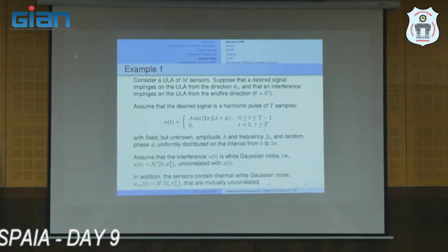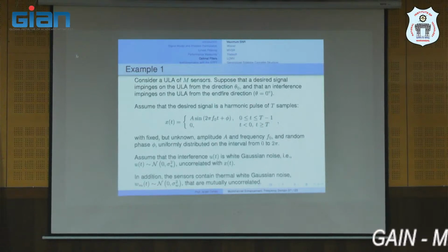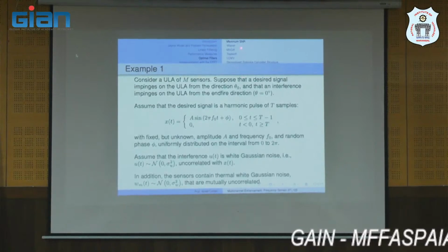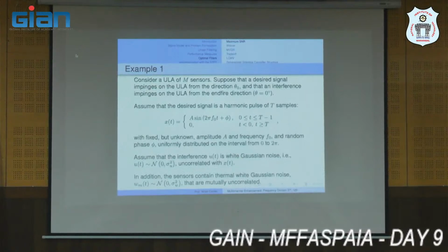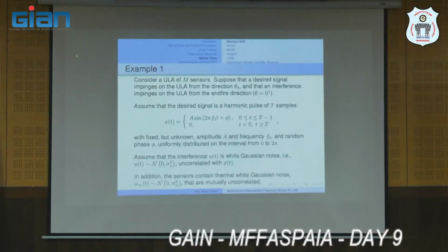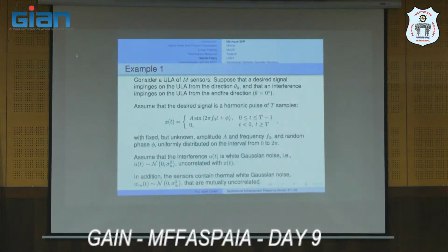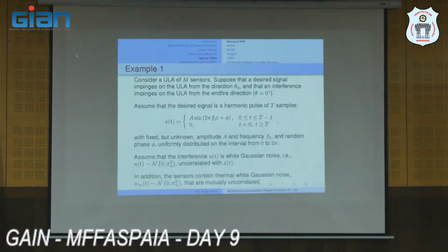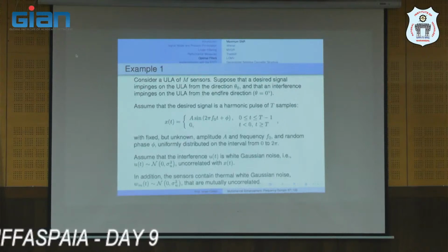So we reduce noise in the noise-only space. And then we have also the LCMV. The LCMV, in terms of output SNR, is less optimal than the MVDR, but if we know that we have another interference, which in terms of noise power is not that significant, maybe its power is weak, we want to give that source more weight.